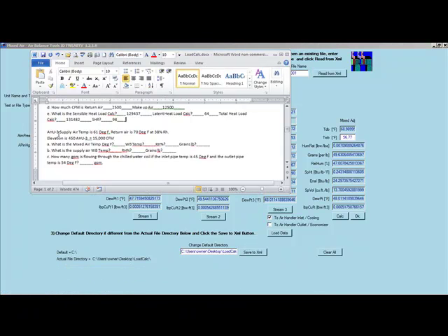We have a supplier temperature, same thing, 61 degrees. Our return in this case is going to be 70 at 38% RH. The elevation is still 450, and the CFM is still rated the same at 15,000 CFM. And then we want to know the mixed air temperature, wet bulb, relative humidity, grains, and what is the supplier wet bulb, relative humidity, and grains. How many GPMs are flowing through the chill water pipe if the inlet pipe is 45 degrees and the outlet is 54?